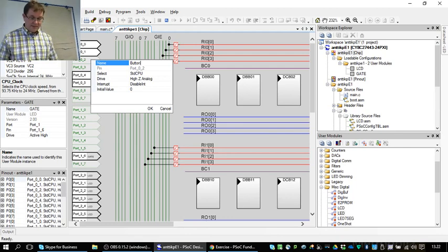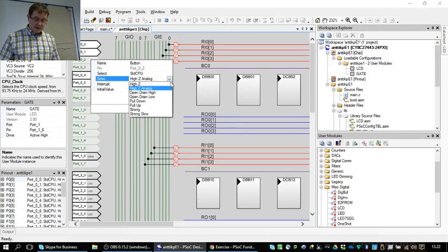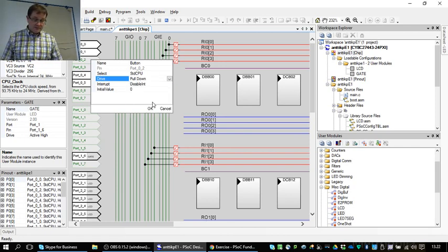Button, there. And that's standard CPU, meaning that it's just a normal signal going to registers that this MCU is actually reading. And then there's the drive. All right, 8 different drive modes. And I want pull down mode. There. Drive is pull down.